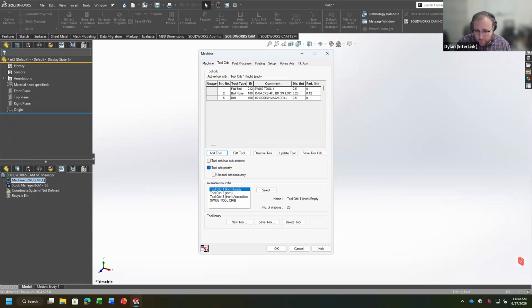But anyway, one of the things we do in Mastercam, and actually I think this will be useful, is the tool cribs. We can set up a different tool crib for whether we're running stainless, aluminum or plastics, because we have a standard layout where we put our tools for different things. I don't know if we really touched on why you might set up different tool cribs.